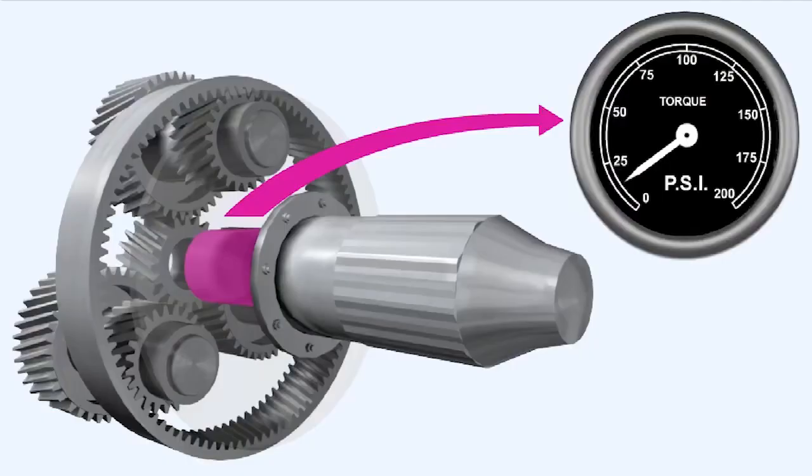To reduce the workload on the pilot in the event of an engine failure, some propellers are equipped with an auto-feather system. The system is normally active during takeoff and cruise conditions only. For example, on a turbojet engine, with the high-pressure fuel cock open and the power lever set to high power, a signal of low torque from the engine torque meter system will automatically feather the propeller. Should either of these conditions not be met, the auto-feather system will be rendered inactive.